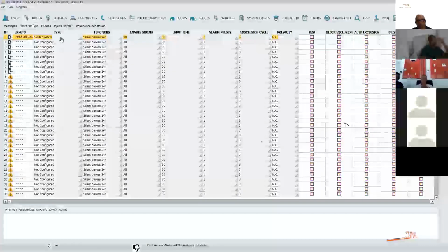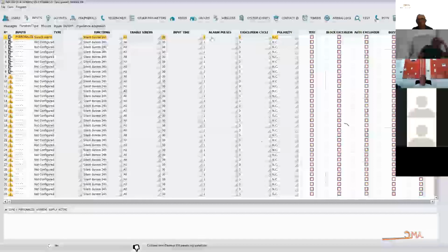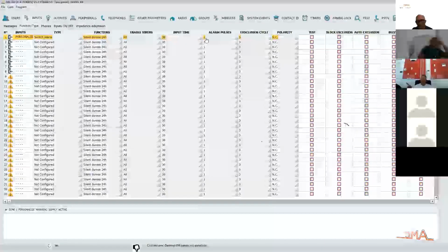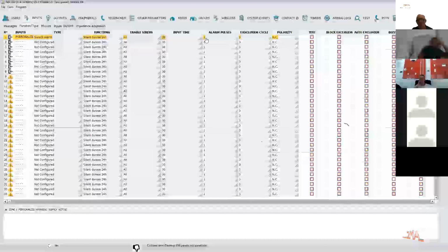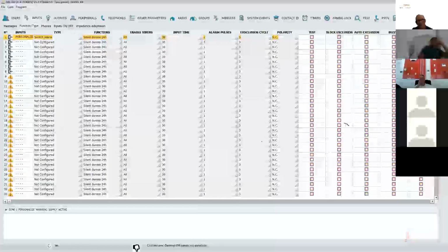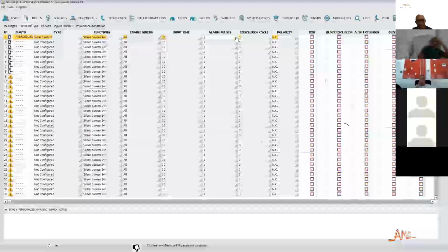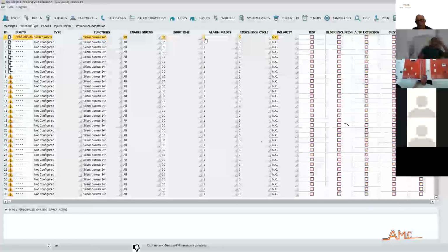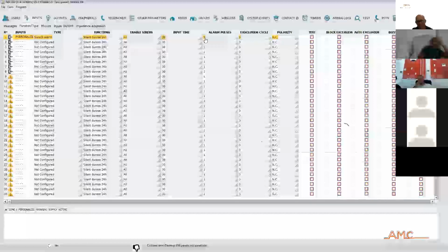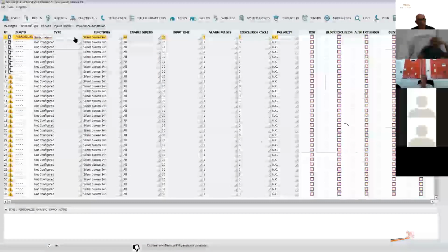For example, if you use a vibration sensor, this system works with the pulse counter. When you set this function, it's important that you set the alarm pulses. If you set only one, it is dangerous because you risk a false alarm. It's better to select, for example, five pulses. In this way, the vibration input works with the pulses. Tell me if it's clear. Is clear? Okay. I continue.